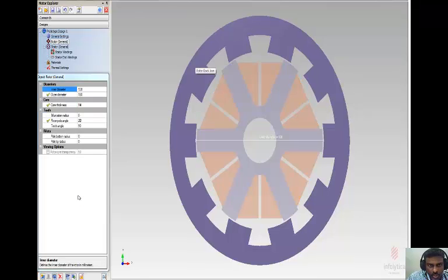The next one is, click the rotor. The rotor here is going to be this one. This is the rotor back end, rotor teeth, rotor pole angle, slot depth, and rotor inner diameter. The inner diameter is going to be 128 mm, outer diameter is 180 mm. So inner diameter is this one, the tip.